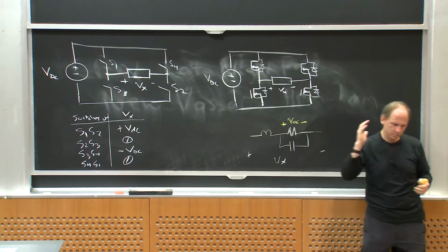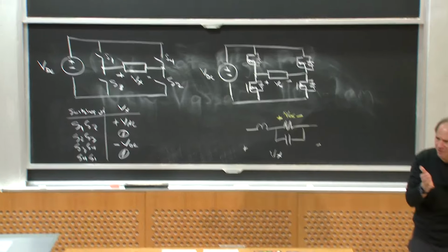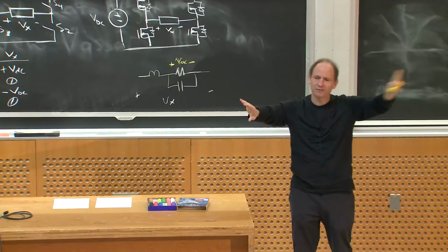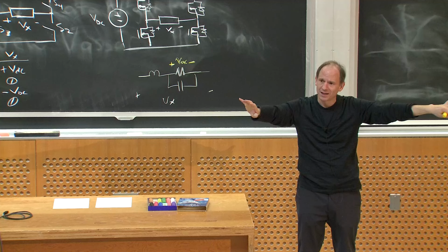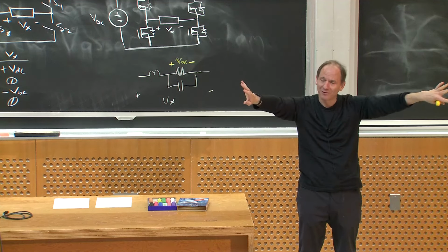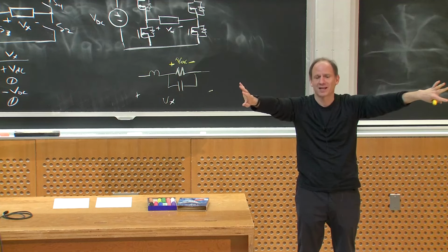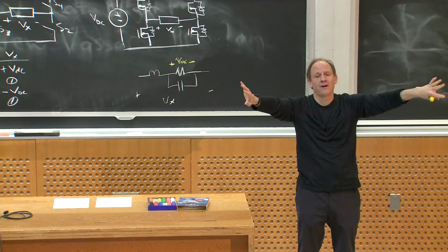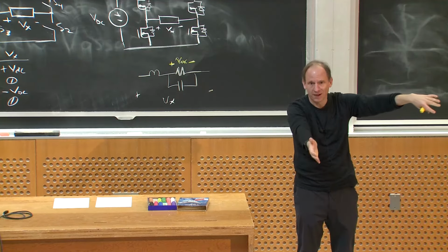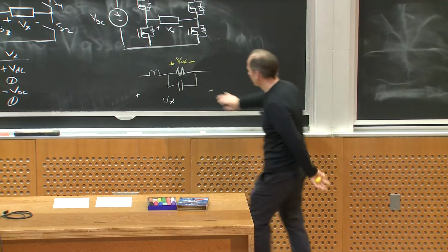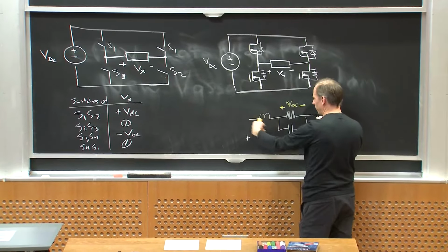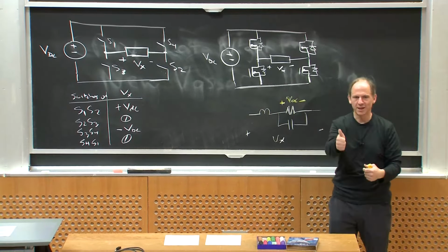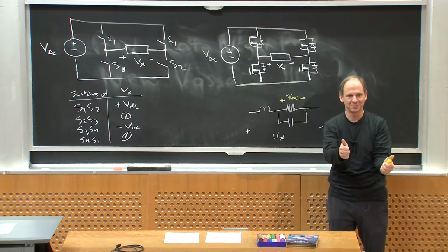When we thought about DC to DC converters, I'm trying to separate out DC from any AC stuff. That's kind of easy, right? Because they're kind of infinitely separated in frequency, or at least on a log scale. If I'm trying to separate out some fundamental that I want to create, but I've got a second harmonic nearby, I need a very good filter to keep 1 omega t and kill 2 omega t, right?